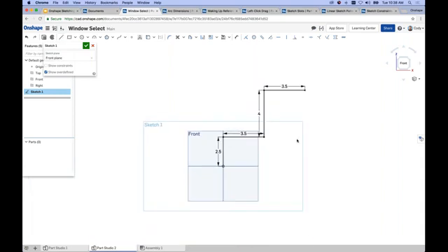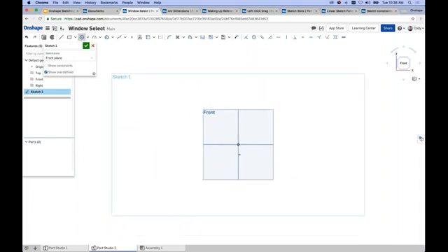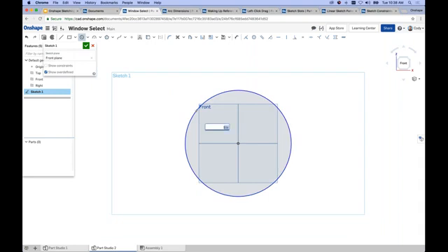And it's not specific to lines, right? So let's window select here and delete. And let's say I'm placing a circle. Same thing. Left click, 8, enter, and now I've inserted a circle and dimensioned that circle, right? Just by typing in a value immediately after placing it. So that's a commonly asked question.